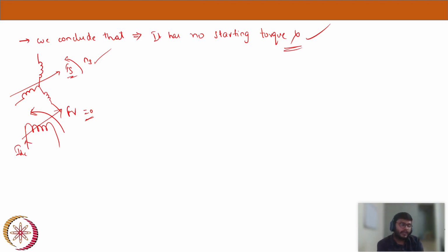Therefore, what I can conclude is, for a synchronous machine to work, my rotor must also run at a speed which is the same speed as the stator RMF. So that's the conclusion we have drawn: it has no starting torque. Another conclusion is,